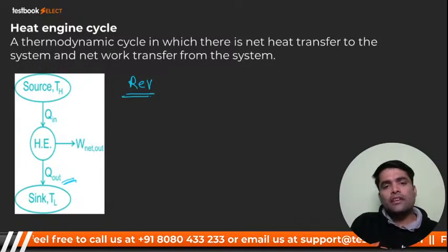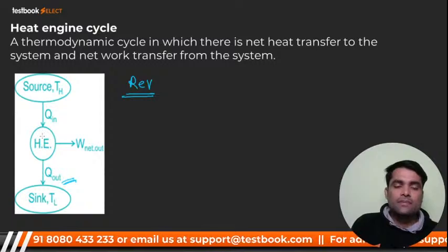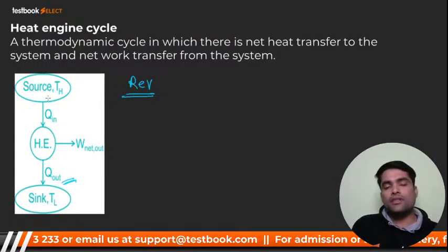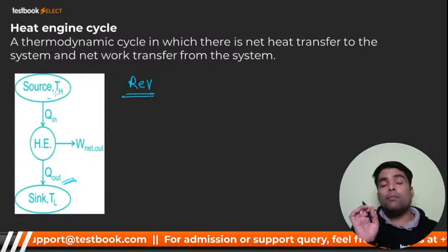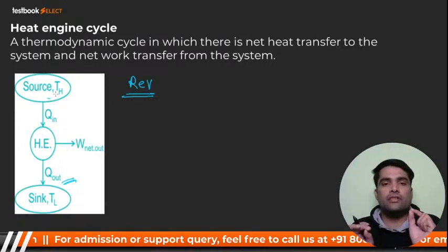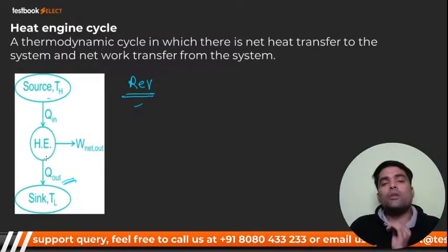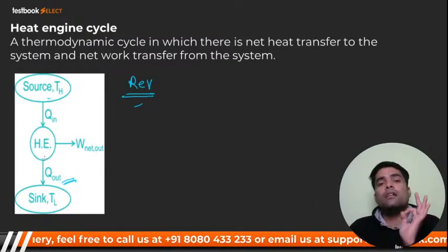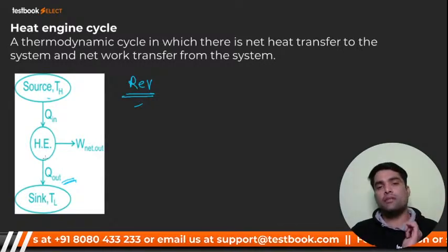Now, my dear, I will discuss one concept. If any engine is reversible, what is meant by that? I will tell you. It can take heat from the higher temperature, that is the thermal energy reservoir, with a very small difference between the temperatures, then and only that process is going to be reversible, right? And the same thing is happening, it is going to reject the heat with a small temperature difference, then and only we can say that the engine is completely reversible, right?